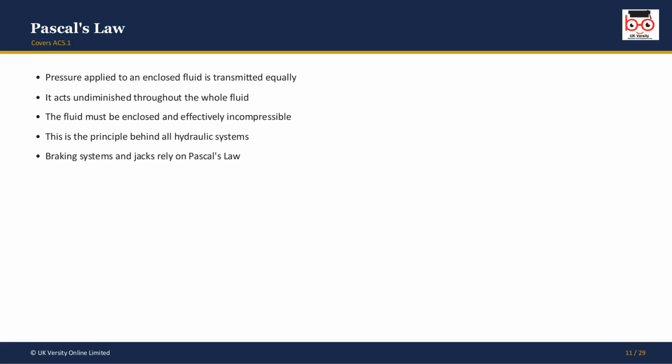Let's meet Pascal's law. It says that when you apply pressure to an enclosed fluid, that pressure is transmitted equally and undiminished throughout the whole fluid. For it to hold, the fluid needs to be enclosed and effectively incompressible, which liquids are. This is the principle behind every hydraulic system you'll come across. Car braking systems and workshop jacks both rely on Pascal's law to carry pressure from where you apply it to where you need the force.